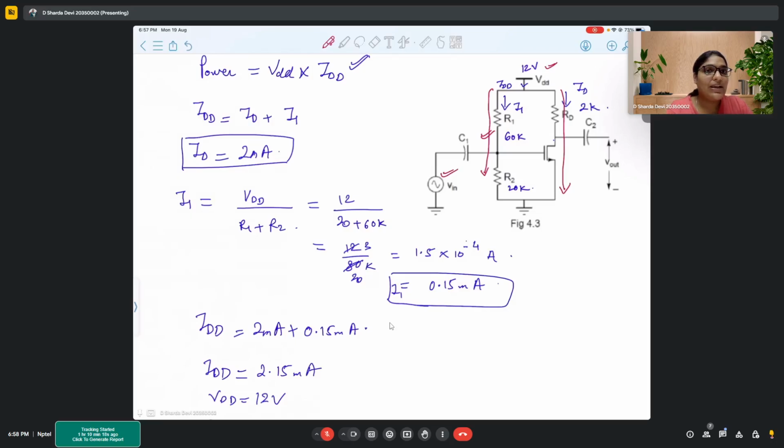So it's more like from the output side the things are fixed. VDD is fixed. Now, with increasing gain, what you can do, you can either increase your Vout or reduce Vin, right? So, what we use is we reduce the Vin. So it basically increases the range of signals.